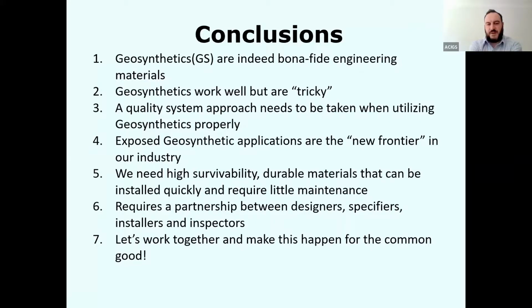Yeah, thank you. Another one here. So GRI GS29, the connection test for pull-out failure of geosynthetics. Is it suitable for geomembranes? Oh, certainly. We've actually done that. The scrim reinforced membranes for exposed geomembrane covers. So yes is the answer.